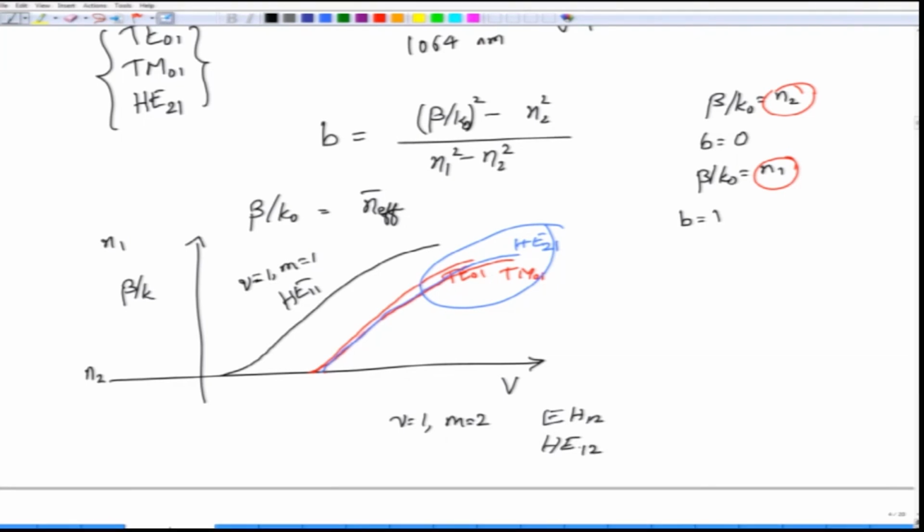And you do get these solutions as the next solutions. However, they will have a propagation constant that is determined in this fashion. So, this is the HE12 solution, and then you also have the EH12 solution, or rather in fact you do not get the EH12 solution, at this point you start getting the EH11 solution. EH12 will come even later than this one. So, you also have another mode which is HE31, which is going in between these two.